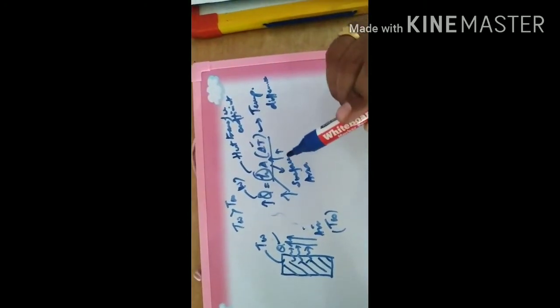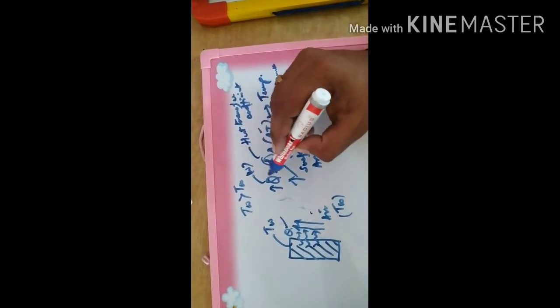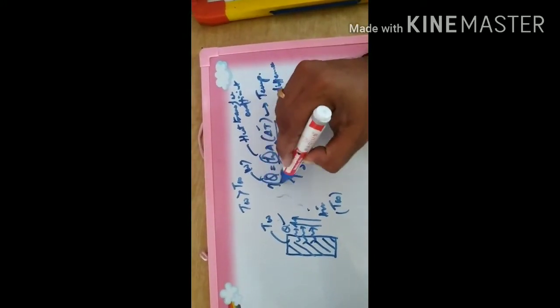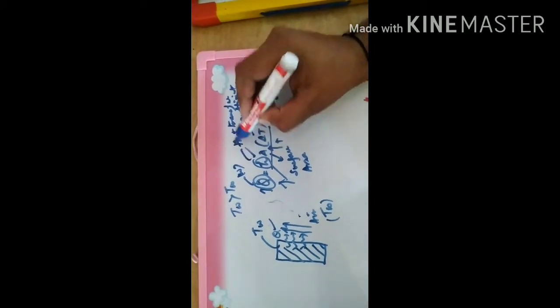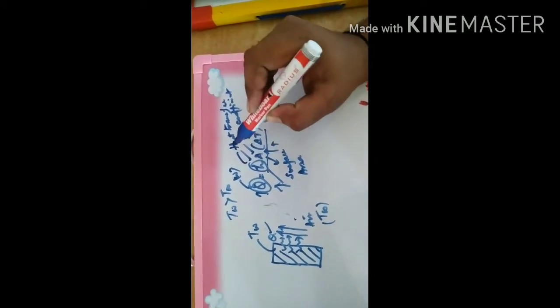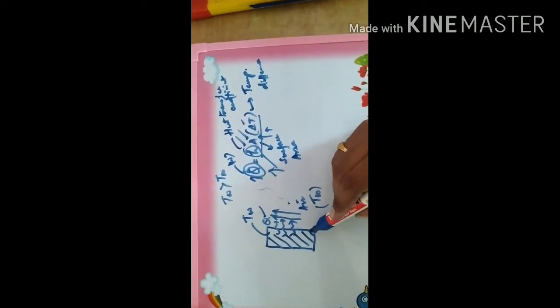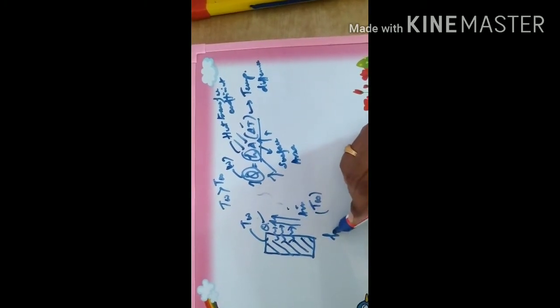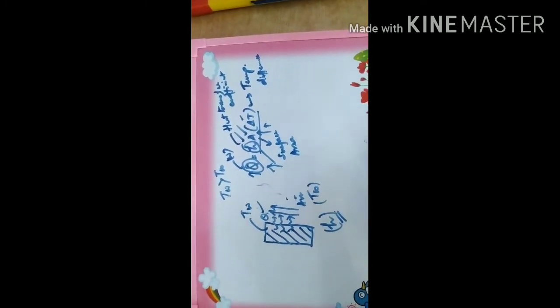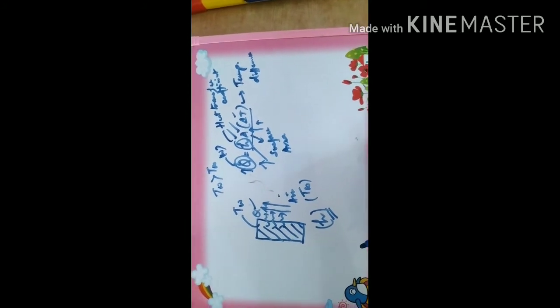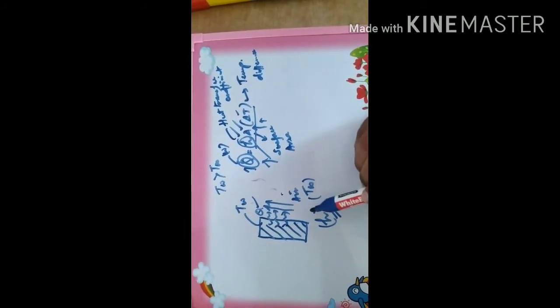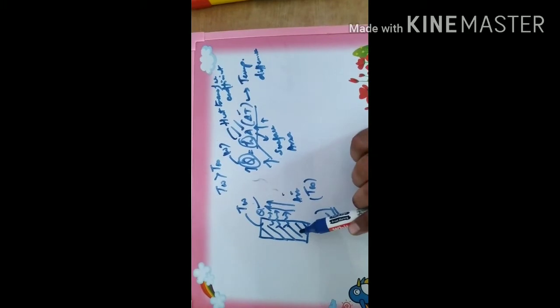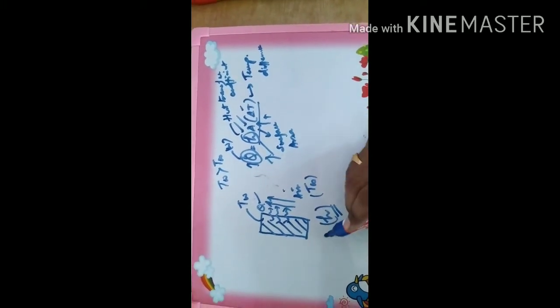So in Newton's law of cooling, to increase the value of Q, either you have to increase the value of h or you have to increase the area. It is already known to us that between a surface and a flowing fluid, h is generally constant. If the fluid is air, the h value between the surface and the air will generally be minimum. It will be very less.